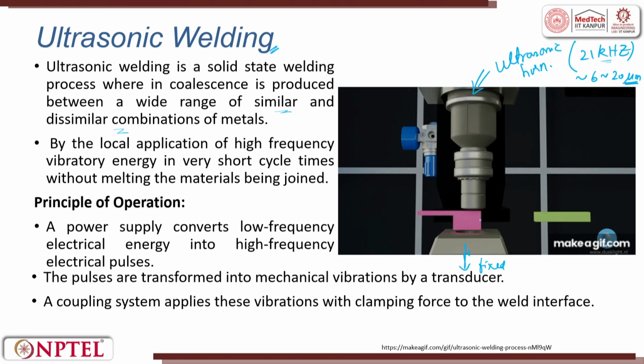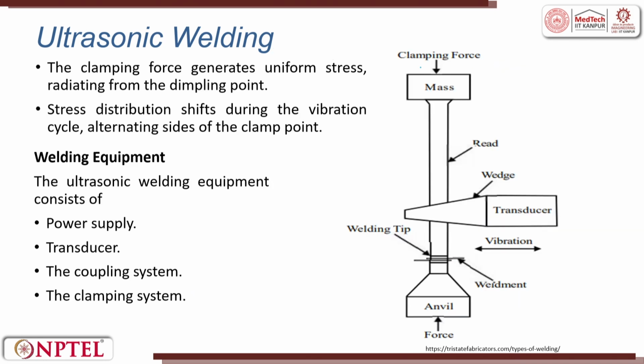In the operation, the power supply converts the low frequency energy into high frequency energy pulses. The pulses are transformed into mechanical vibration by a transducer. Once there is vibration, there is cleaning and heating. So, diffusion happens. Here is the clamping force. The clamping force is given by a mass. This is the holding.